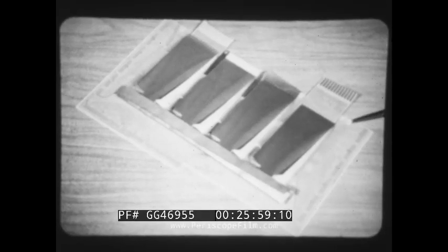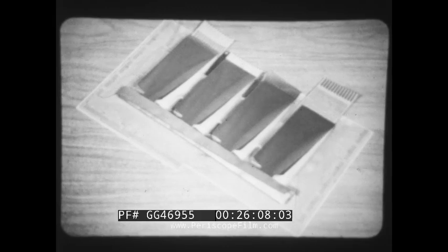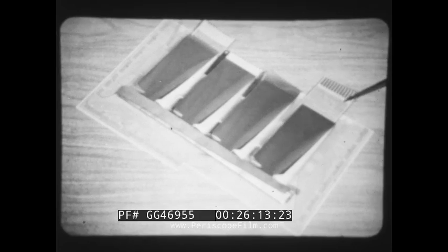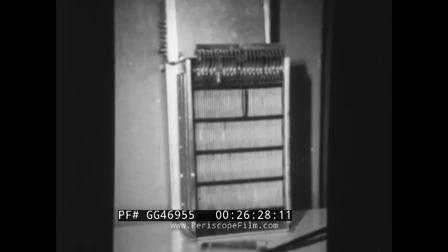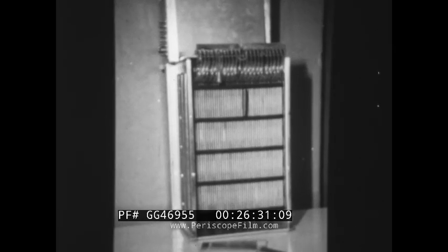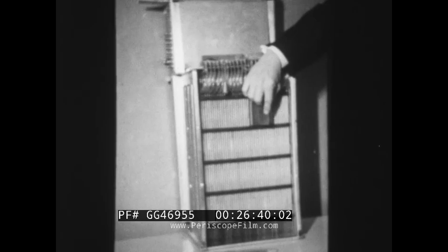Here again we see an exploded view of the type of microprogrammed card capacitor read-only storage as is found in the Model 30. This unit happens to be the sense board. This is an example of the microprogrammed card itself. Here is a view of a full module of read-only storage for the Model 30. It happens to represent approximately 4,000 words, and here you see a separate microprogrammed card. You can see the ease, in the case of the Model 30, of inserting microprogrammed cards or changing microprogram instructions.